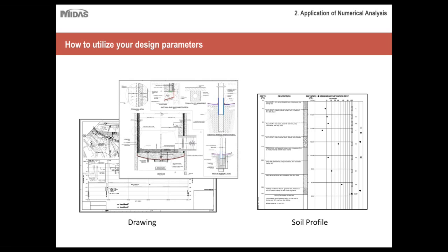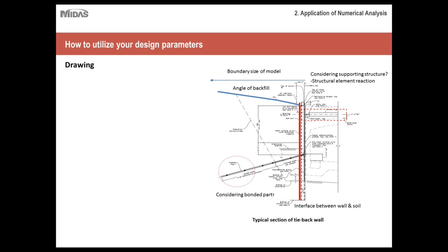And then also your soil profile. This should look familiar. You need to know what sort of soil you're dealing with, the profile or the soil strata, so how deep each layer is. And you need to have your soil parameters ready and at hand.